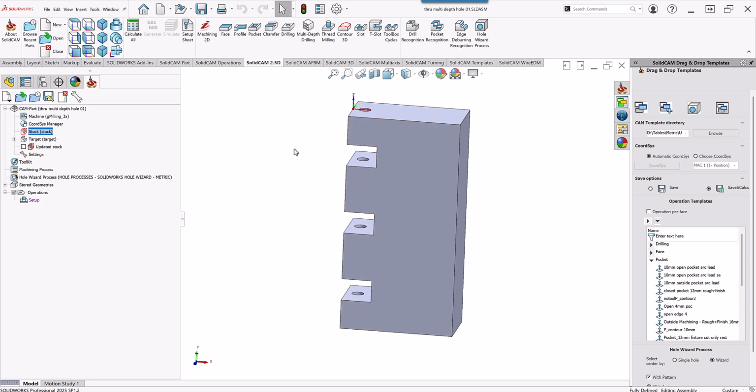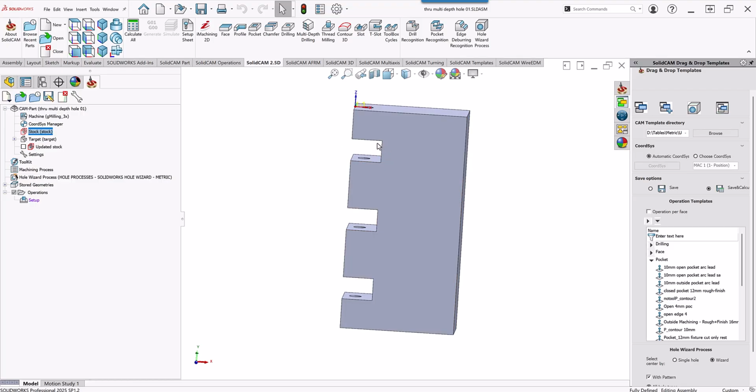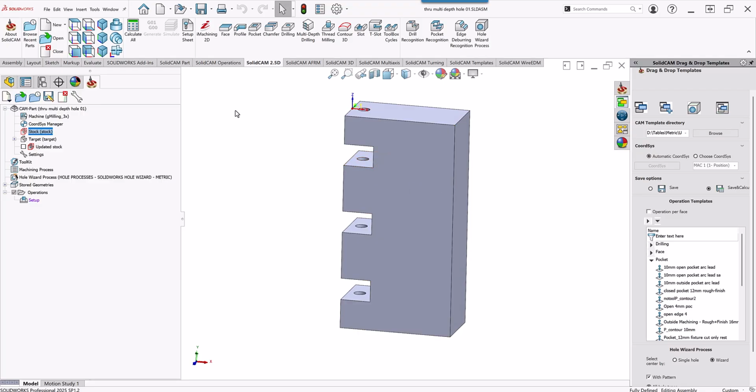Now, this is used for very deep holes, or if you have breaks in the holes, just as you have in this part over here, where certain areas are already machined and there's no reason to go here in a drill feed, you can go a lot quicker. The same thing over here and over here. And like I said, this is not a canned cycle. So let's take a look at how this works.